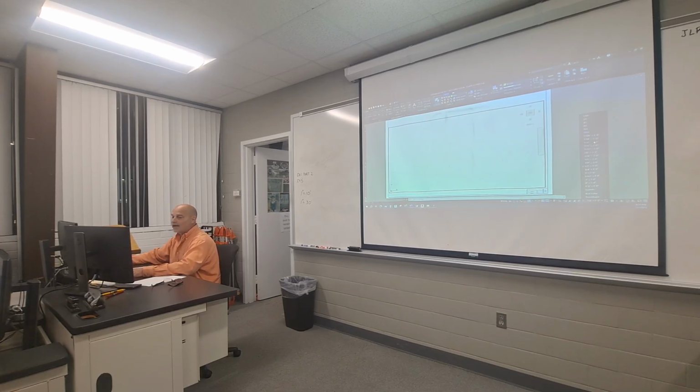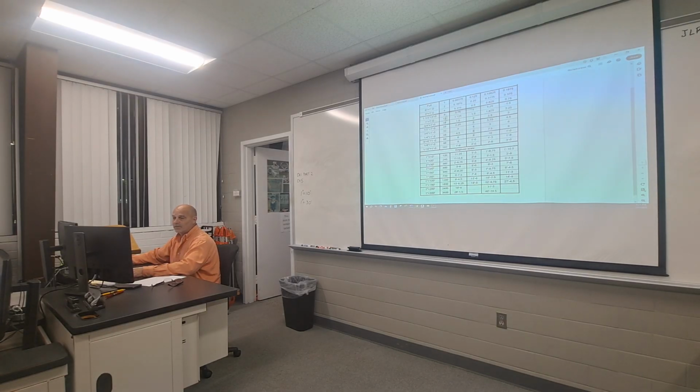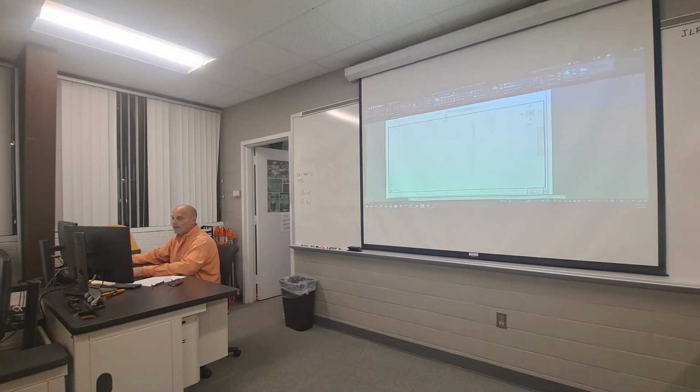The way you will add those civil scales, these scales down here at the bottom. So you remember I said 1 inch equals 10 feet is a magic number or a scale factor of 120. If I come over here in AutoCAD and I pop this up, I'm gonna scroll all the way to the bottom, select custom off that menu. That's gonna pop up your edit drawing scales dialog box. Remember, we're just editing in this drawing alone.